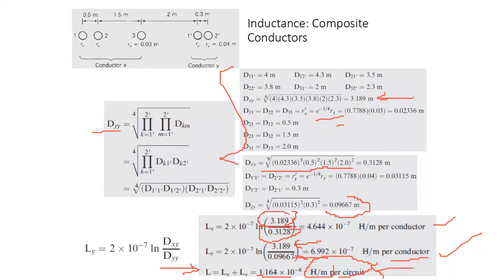So we add them together. Okay, if we want the complete, but we don't do this. We'll come to this one. But when we do a single line diagram, we take only one phase, and this one phase represents all the phases, because the phases are the same. They're only 120 degrees apart. So we will come to the three phases.